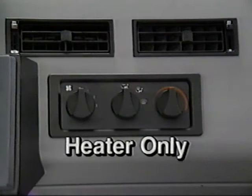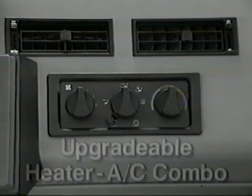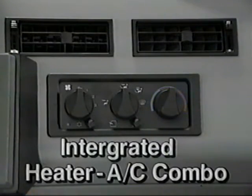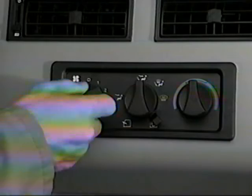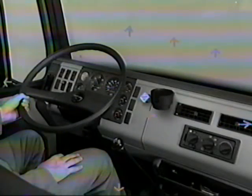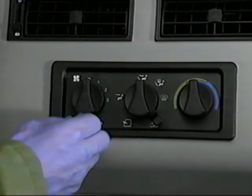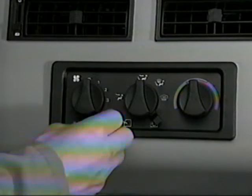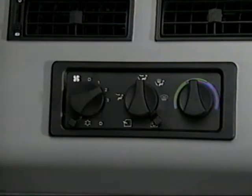The heater AC panel controls and their functions are identical in the FL 60, 70, and 80 trucks and in the MB 60, 70, and 80 vehicles. The 3-speed fan forces fresh or recirculated air to selected air outlets. If the unit is equipped with air conditioning, an on-off control lever under the fan switch turns the AC system on and off. The fan switch must be on for the air conditioner to operate.